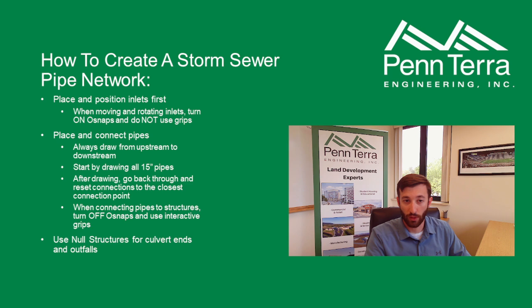And what I've found to work the best when doing that is to treat them like blocks. I don't do any grip editing. I turn on OSnap and I use move, rotate, those basic CAD commands to manipulate them, because that allows you, like on our type C inlets, to snap to the midpoint at the face of curb to move and rotate. It works pretty well. Sometimes using the grips to rotate doesn't work because it rotates about the center point of the inlet. So that I've found to be helpful.